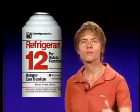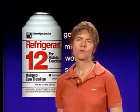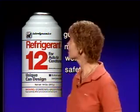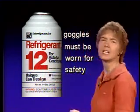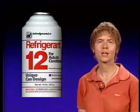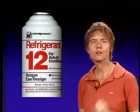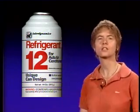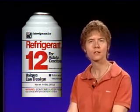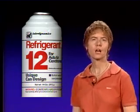Now, when you're working with Freon 12, which is the refrigerant that you normally would use, goggles should be worn because even a little bit in your eyes can be very damaging. Something else to be aware of about refrigerant 12 is that if it passes over an open flame, it changes to phosgene gas, and phosgene gas is very, very deadly. So when you're working with the air conditioning system, working with refrigerant, you do not want to have any open flames around.